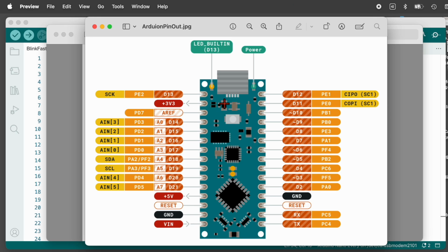The Arduino can get power from either the USB or this VIN, voltage input pin, down here. Note the arrow is going toward the board. And you can have both of these connected at the same time. That's okay too. It also will supply both 5 volts and 3.3 volts to other circuitry. So you can pull off 5 volts or 3.3 volts if you need it.